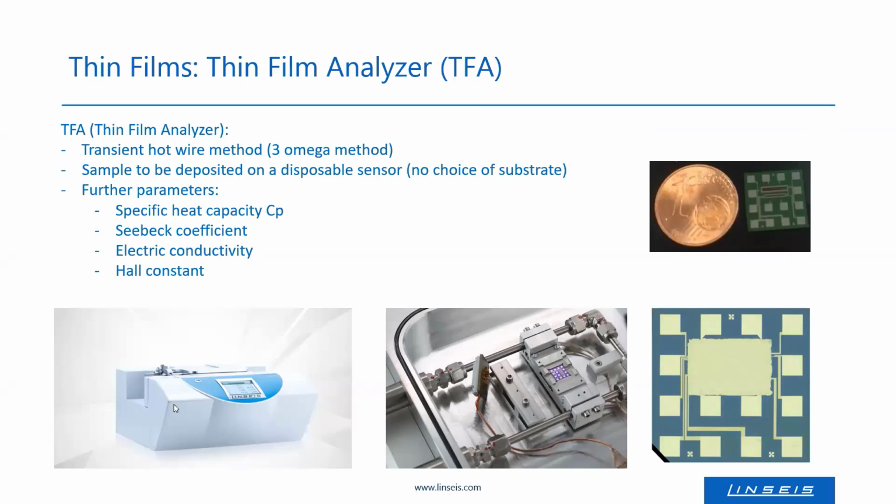And then you can perform a measurement in the TFA analyzer, and you get thermal conductivity and also specific heat capacity. And depending on the configuration of your instrument, you can also measure electrical parameters like the Seebeck coefficient, the electric conductivity, and the Hall constant.